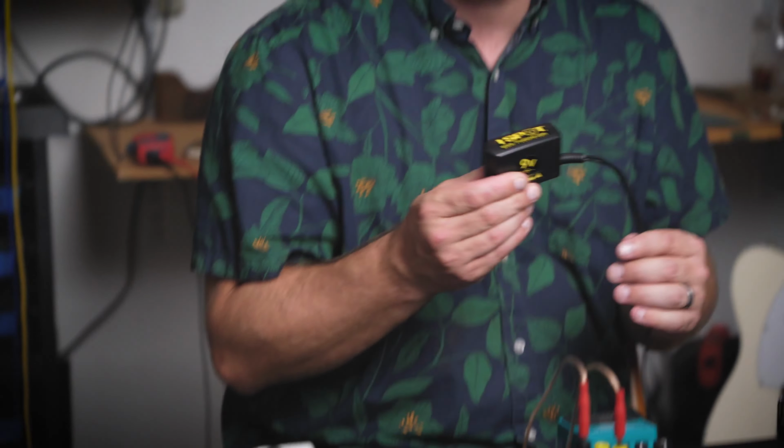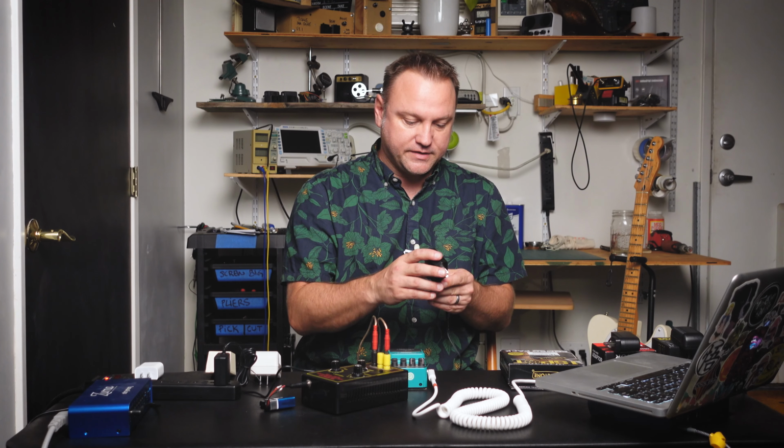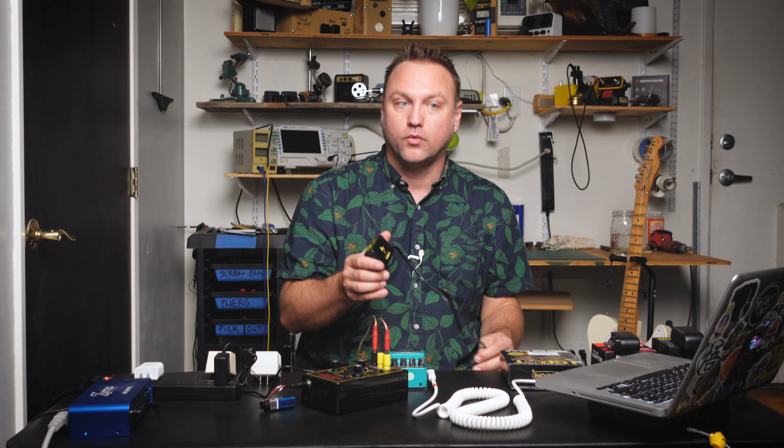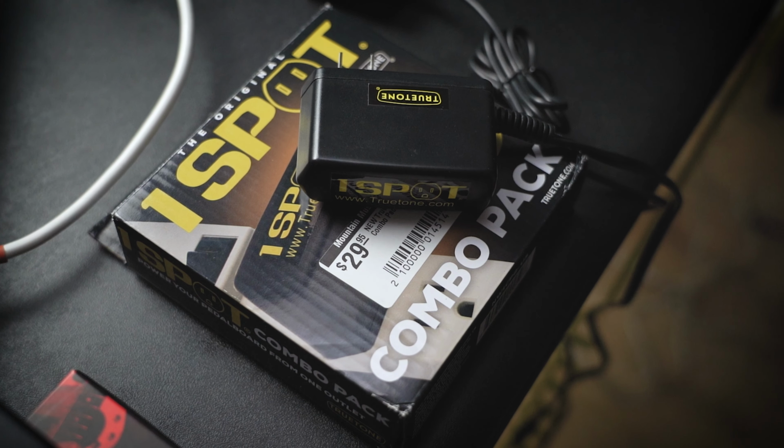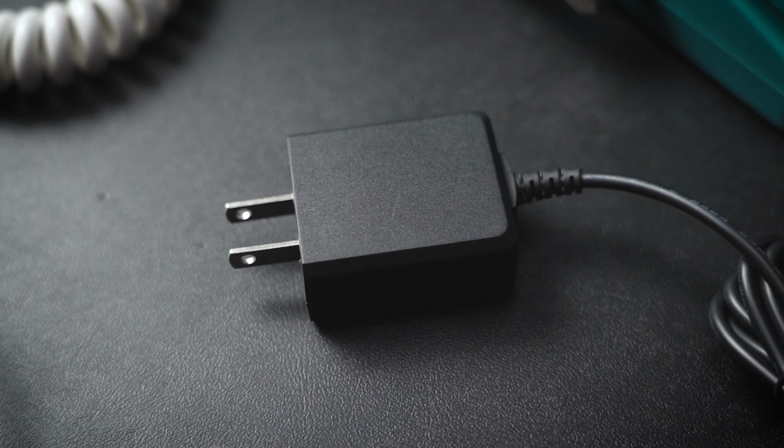These are way more compact and efficient. These are pretty universal when it comes to portable electronics. If your product came with a power supply, it's likely to be a switch mode power supply like this. However, they have a reputation for being noisy, which is no longer the case. Originally, when we had to switch from linear power supplies in the audio industry to switch mode power supplies, they had a bad reputation for being noisy. They weren't really designed for audio originally. They were designed to be used with small electronics and to be really efficient.